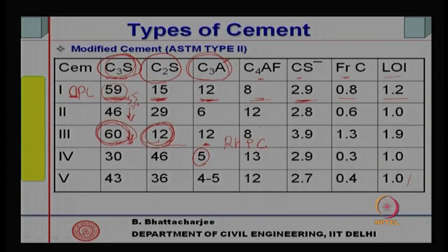Physically, of course, fineness governs. Higher the fineness, rate of hydration will be high, and therefore, strength development will be faster.